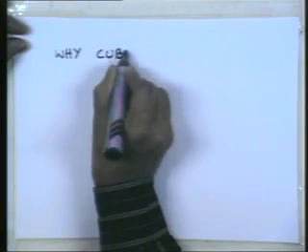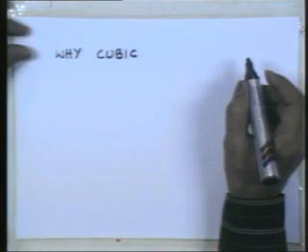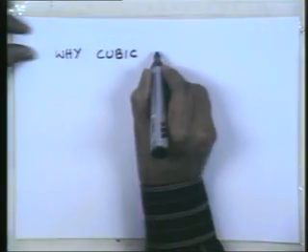Now, if you look at this particular discussion that we have had so far, we have used cubic polynomials. Now, why only cubic polynomials for curve fitting? It is very simply the lowest degree polynomial that allows you to ensure velocity and acceleration continuity. Okay. So, that is the advantage. Why cubic? If you ask the question, why did we emphasize cubic curves being used? Why cubic segments?